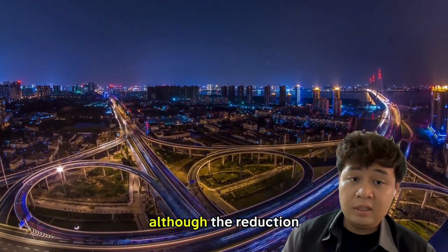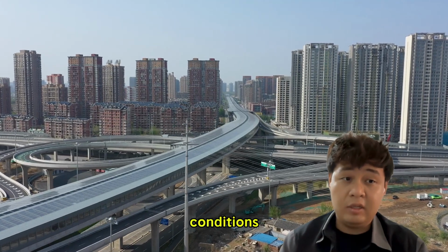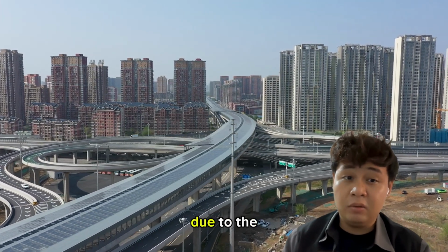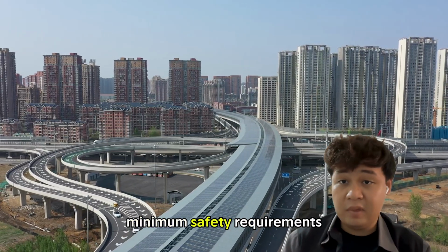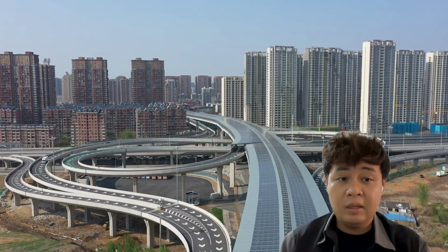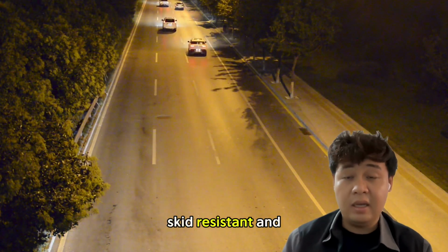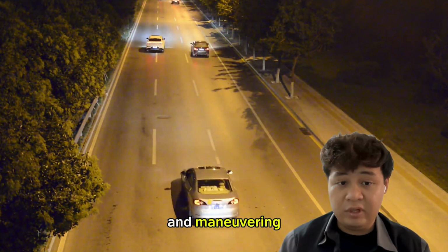Although a reduction in skid resistance was observed under the wet condition, which is expected due to the presence of water, the value remained well above the minimum safety requirements. This indicates that the pavement surface provides excellent skid resistance and is safe for vehicle braking and maneuverability.